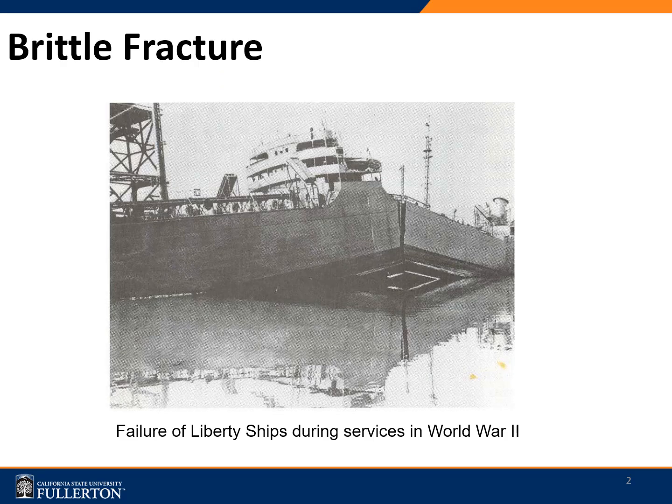So before we talk about impact testing, let's take a look at what brittle fracture is. Brittle fracture is a breakage or cracking of the material into parts. During this process, we don't see any visible deformation on the body. In other words, brittle fracture is a sudden, very rapid cracking of the material or the body under stress, where the material has not exhibited any signs of ductility or plastic deformation.